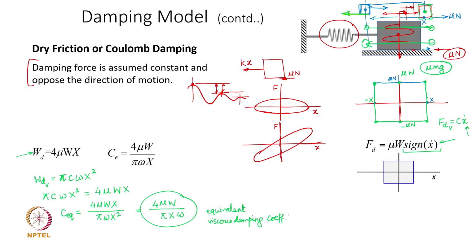Now, the practical significance is that here of course, we have a theoretical expression for a Coulomb damping case, but suppose we have a complex mechanical system and somehow we put that in a cyclic motion and extract the force displacement relationship, or the graph relating the force and the corresponding vibratory motion, and somehow get the area under that force versus deflection diagram. This diagram is a measured one.